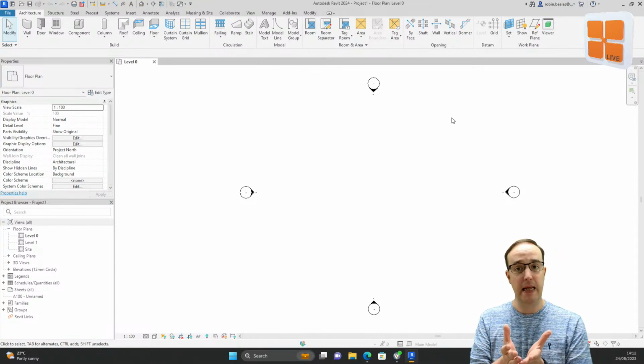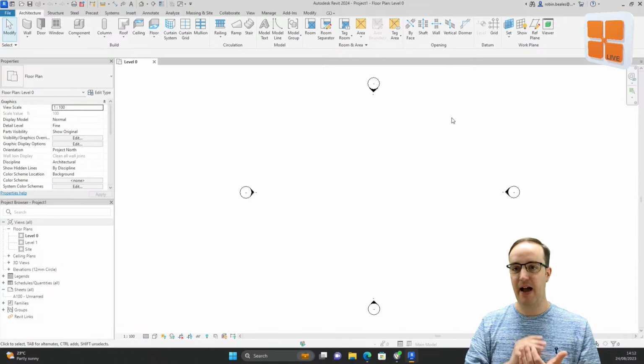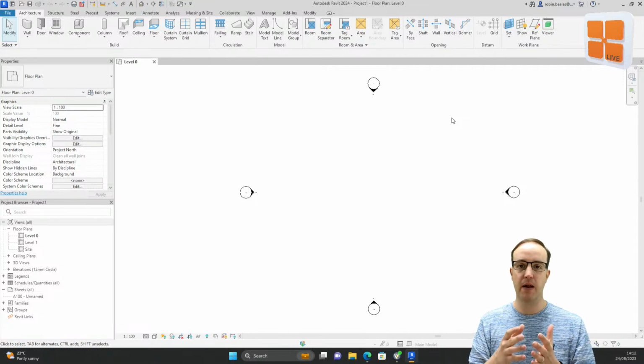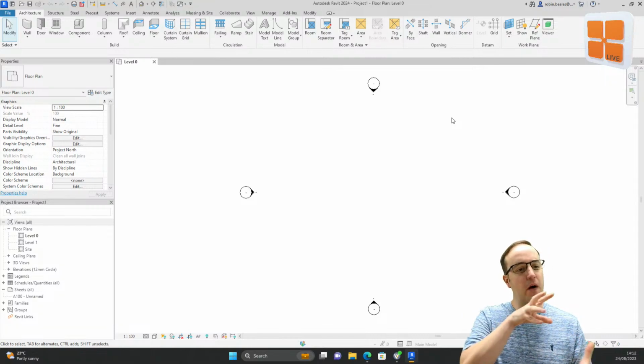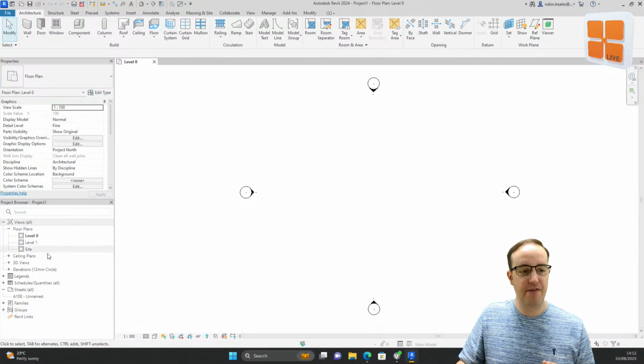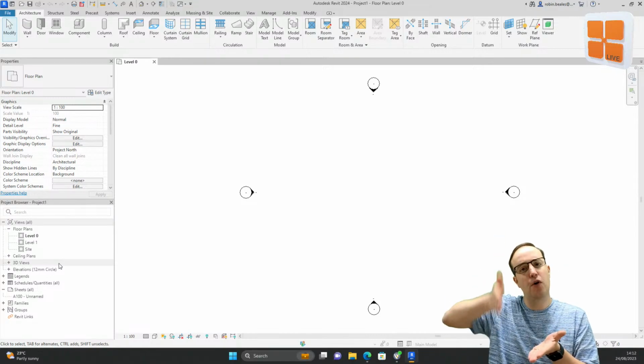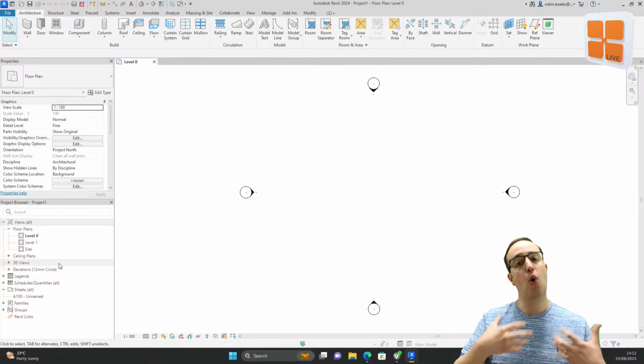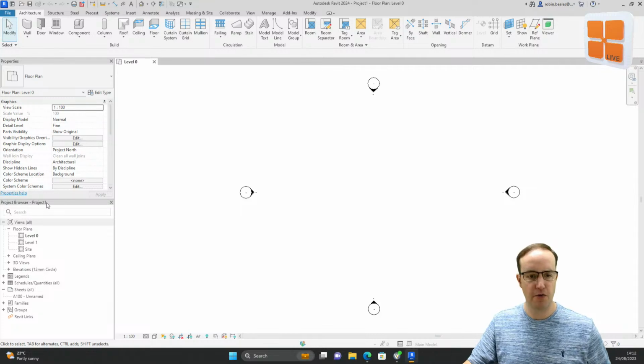But predominantly, and this is what's important for you AutoCAD users, we're going to be editing that in 2D. Actually in Revit, we spend very little time manipulating and editing the geometry in 3D. We're mainly drawing using floor plans and elevations and sections, just like you would inside of AutoCAD. They're just more intelligent. So what we use our project browser for down here on the lower left-hand side is to segregate that model into different views. A view could be duplicated to show more or less information, and we'll get into that as we go through this demonstration.